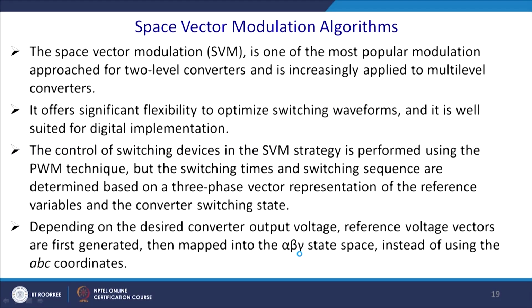The space vector modulation or SVM is one of the most popular modulation approaches for the 2-level converter and is increasingly applied to the multi-level converter. It offers significant flexibility to optimize switching voltage and switching waveform, and it is well suited for digital implementation because it is a 1 and 0 format.